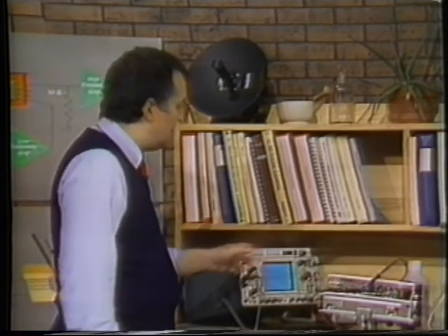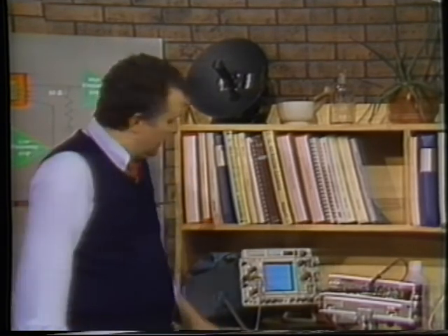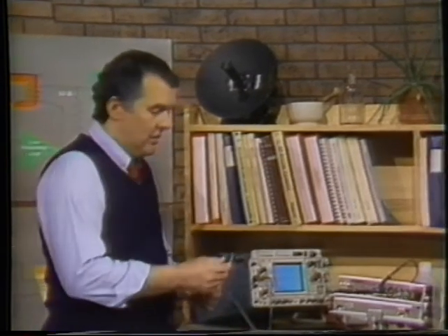How we get that signal to the scope's inputs directly affects the accuracy of our measurement. Do we need to use a probe? Well, the answer is probably yes, we do. The exceptions would be DC or very low frequency signals where capacitive loading is not a consideration, or 50 ohm systems that can be terminated directly at the scope input. And even then, a probe is probably a handier, more convenient tool.